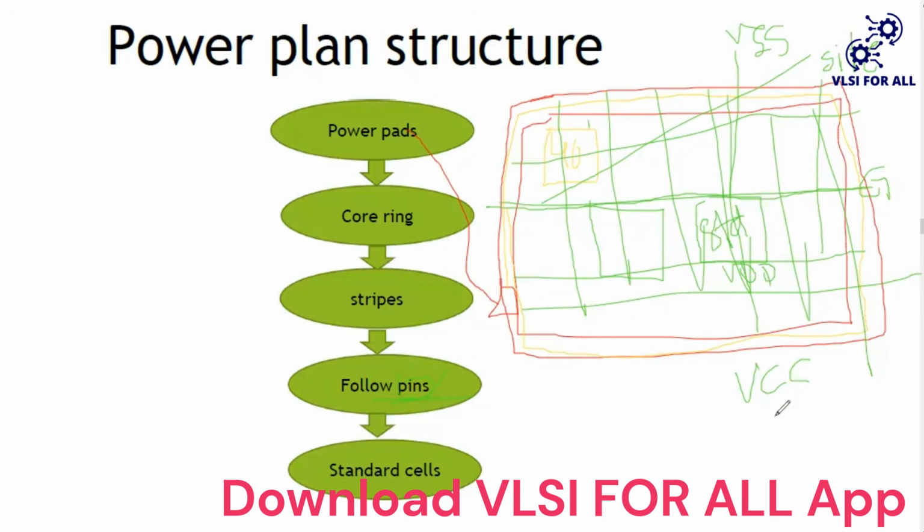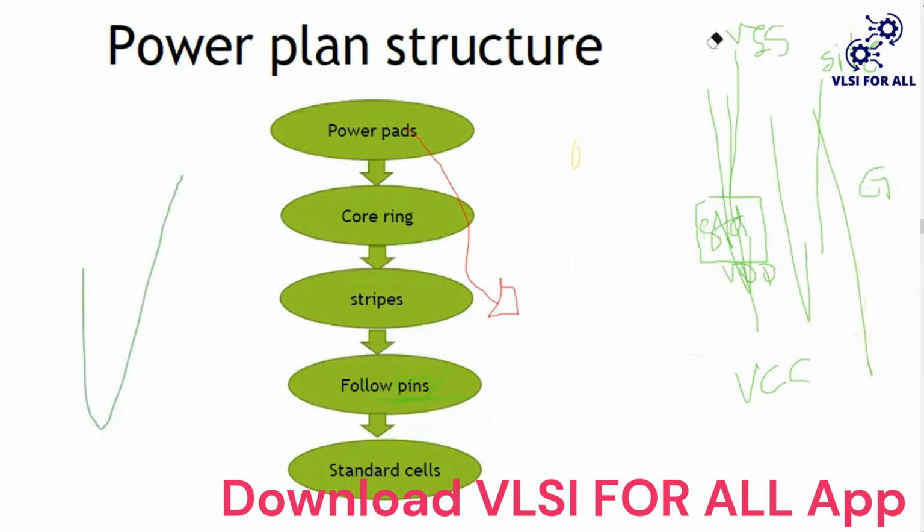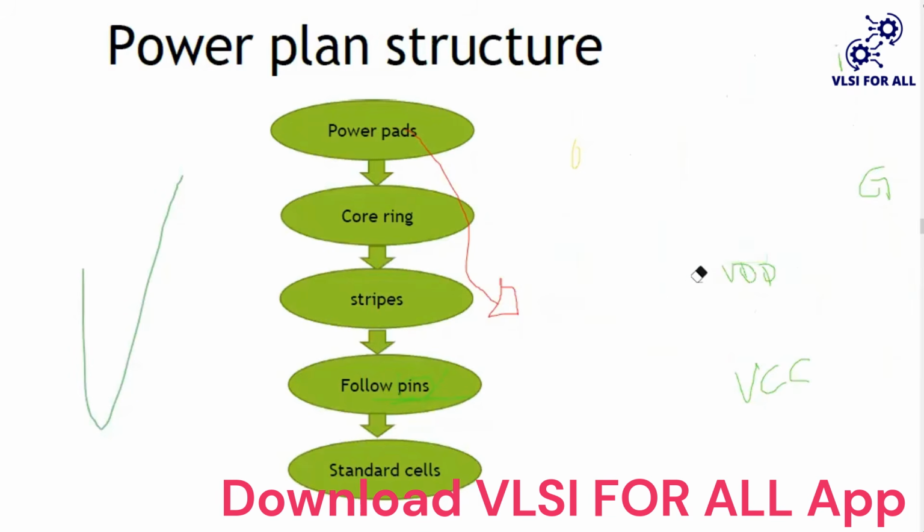Based on your macros analysis, the power domains will be defined. Whatever power domains the UPF defines, at the power plan stage the power will be distributed accordingly. Same structure only. These are the power related infos.